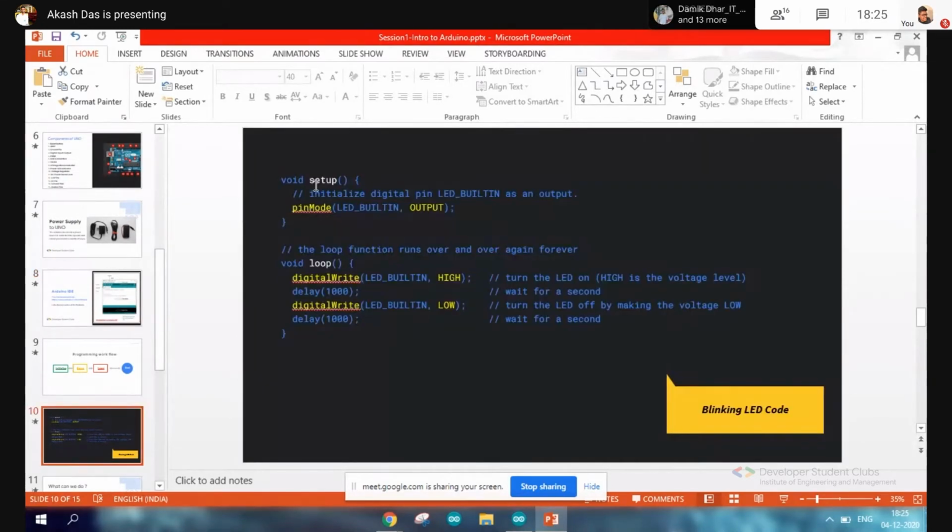This is one of the programs that is called the Hello World program of the electronics world. It is the blinking LED program. As I have said, in void setup, it initializes the digital pins or initializes the pins that are there. So it's the syntax of initializing this pin as output. It is a blinking program. So the pin is made output. It is written as pinMode LED_BUILTIN, OUTPUT.